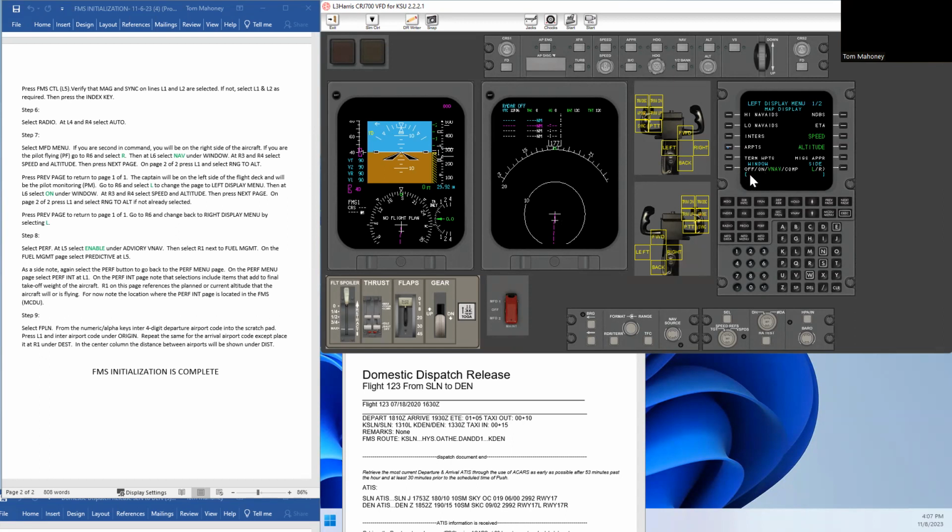If you are the flying pilot, and today the flying pilot happens to be flying on the left side of the aircraft, you would select the left display to read in VNAV. Then you would verify that you were selected in speed and altitude, which if you'll notice that my menu will change slightly, it did not there. But to illustrate how this changes your MFD, take a look what happens when I select airports. So the lineup pulls up. And if I wanted to select intersections, I could pull those up. I could select high nav aids.